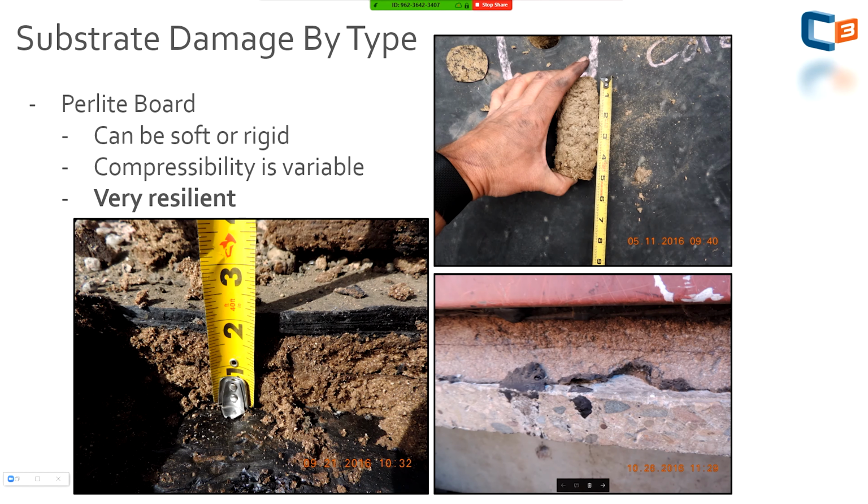The insured reported no leaking. We'll get into that in a minute. But it was soaked. And unless we did a cut, the built-up field was fine in this case. It was only the transitions. So unless we did a cut, unless we had the right tools, we'd never know that this really required replacement and not just a repair or replacement of the transition flashings.